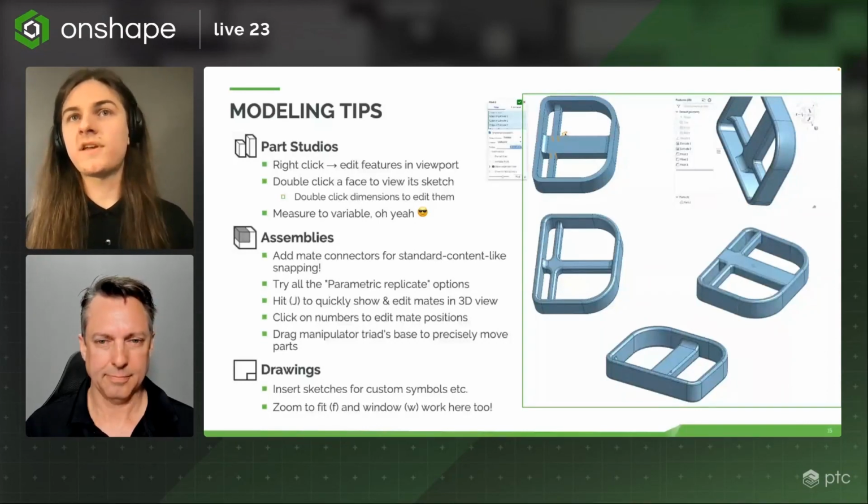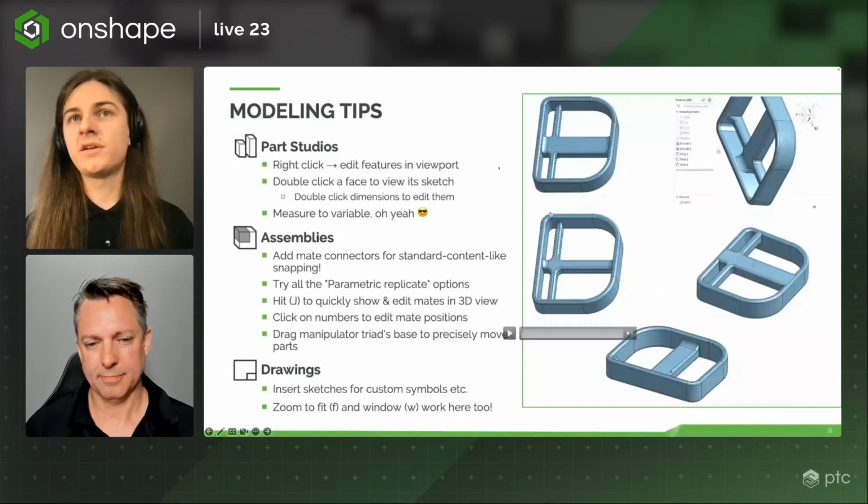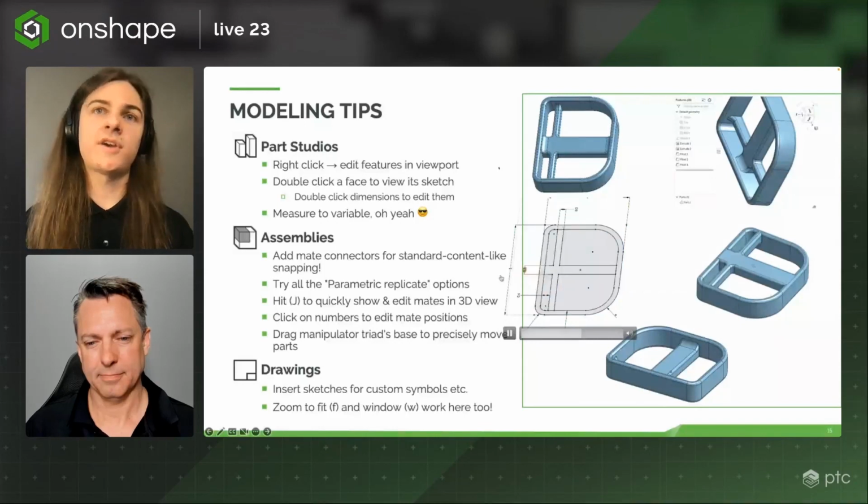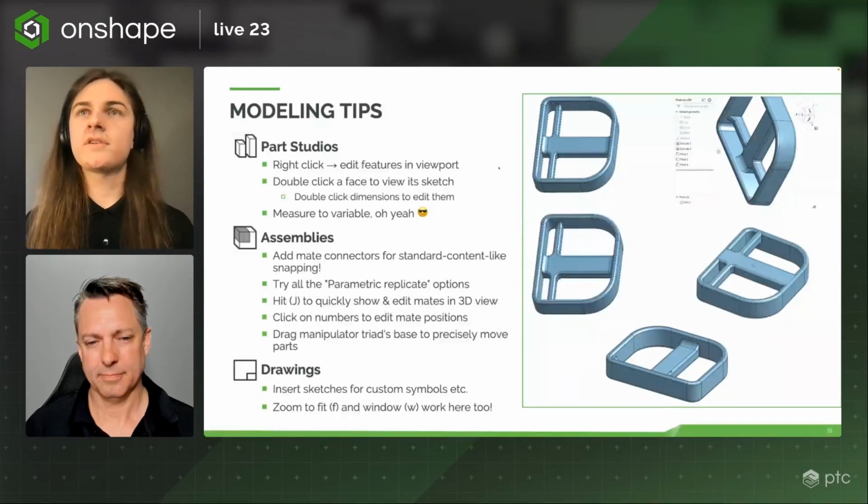Additionally, you can double-click faces to view the sketch that's responsible for generating it. So here I can just double-click that face and I can immediately see the sketch, and I can double-click a dimension to start editing. That saves a ton of time if you have a ton of sketches. Additionally, there's other useful things.